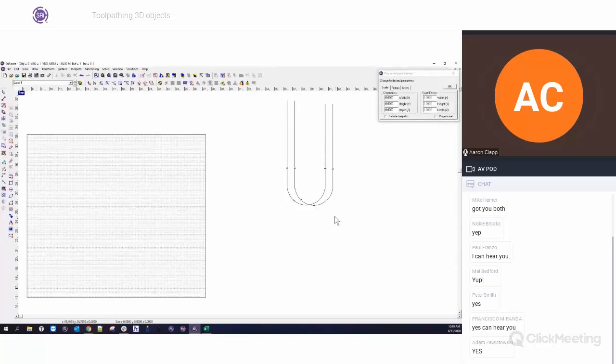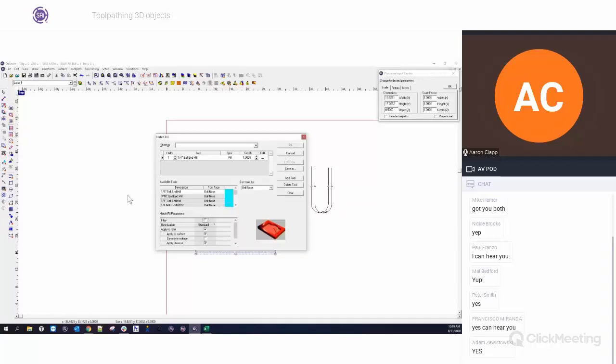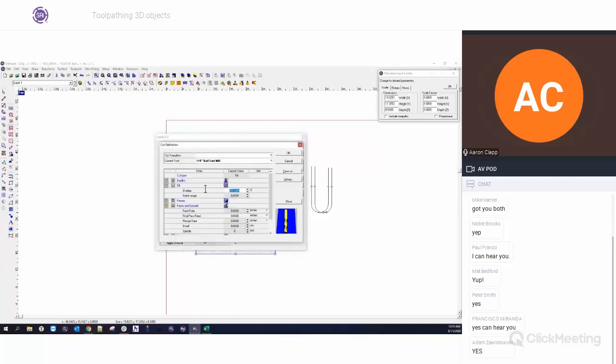So now we've had this visual, okay? So we know that that's going to happen. So how do we deal with this in our relief? Well, we go into our toolpath, and this is where we change our overlap. Typically a 50% overlap is going to give you a lot of little lines and little humps everywhere where the toolpath missed some, and that's just the nature of the profile of the tool.